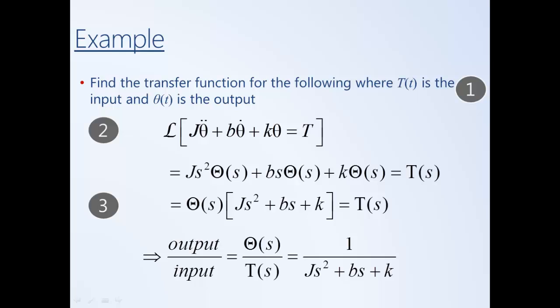And the transfer function does have units, where the units are the units of the output divided by the units of the input. We'll just make an assumption, say that the angular displacement or the angular twist is defined in radians, and let's say the torque is defined in newton meters. And so these are the units of the transfer function, but they don't necessarily tell us anything about the internal structure of the system. So we don't necessarily know what the coefficients in the various polynomials mean, what they physically represent, unless we derived it from first principles.